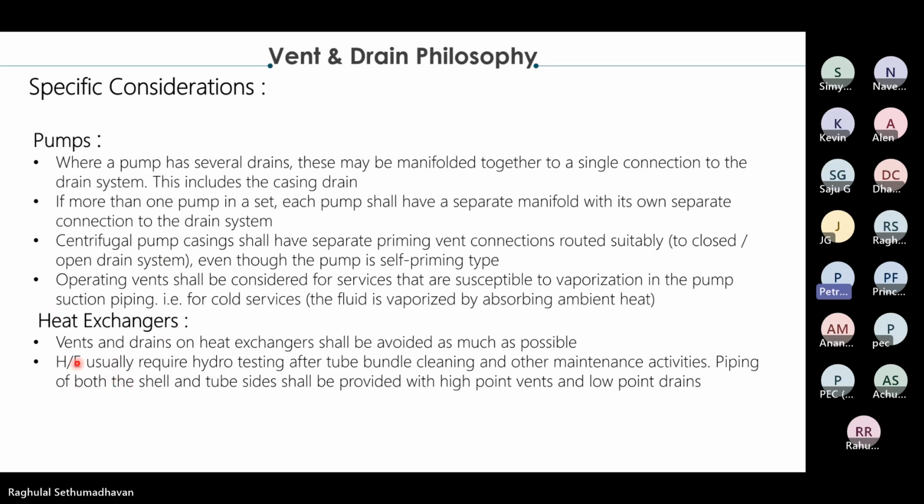For heat exchangers also, vents and drains will be avoided to the most extent. Usually only the hydro testing vents and drains will be provided on heat exchangers. Central drain, in some cases, will not be operational. Even if it is there, that will be only for maintenance. That also we can club together with the hydrostatic testing vents and drains.